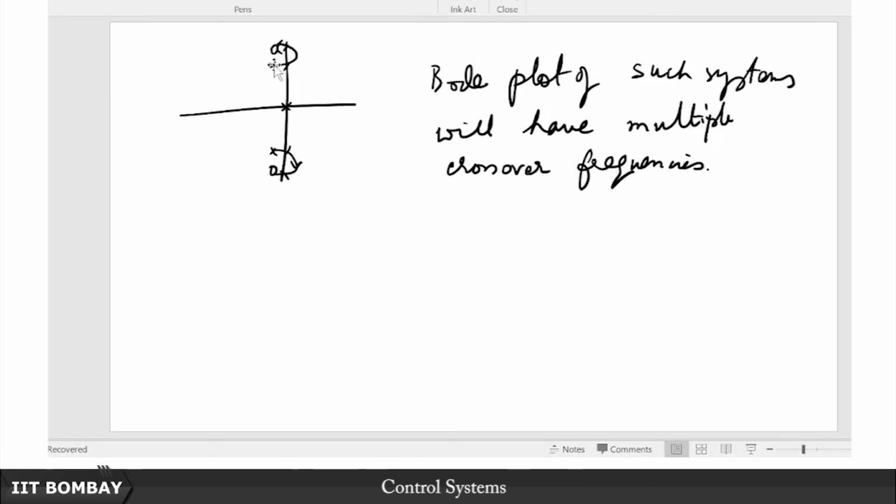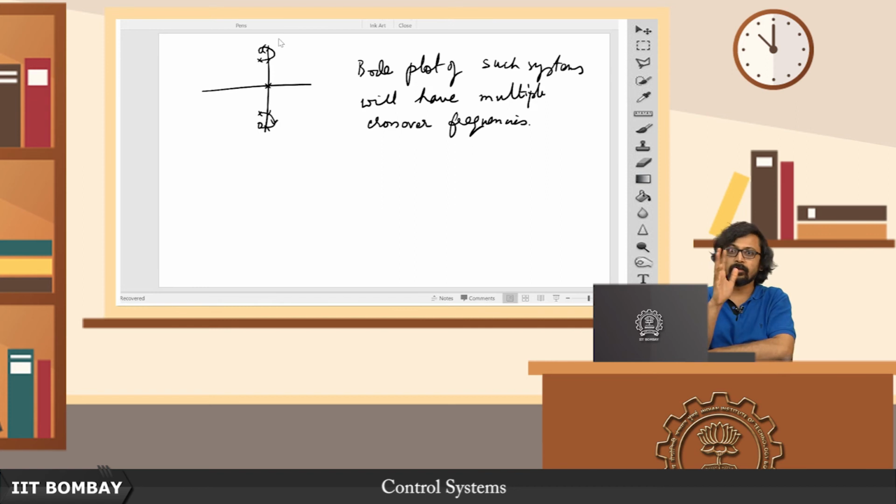First scenario, when you are going from the left half plane to the right half plane, that is one brink of stability and instability. The second scenario is when you have another value of omega at which you are going from unstable back to stable, and now all our understanding about positive gain margin and positive phase margin being the thing to desire goes out of the window. In general, unless you meet such rogue systems, we always go with the convention. But that is why I want to always put in a caveat: do not go by all these conventions all the time, use whatever understanding you have grasped about systems.